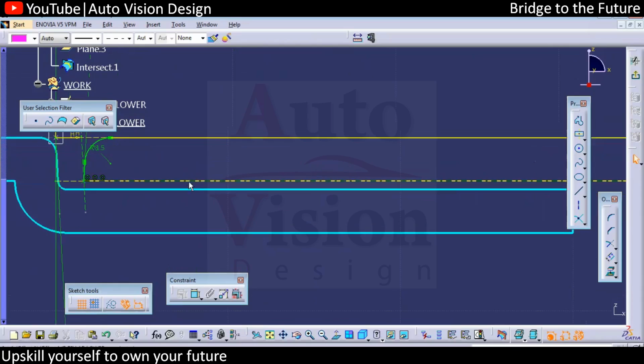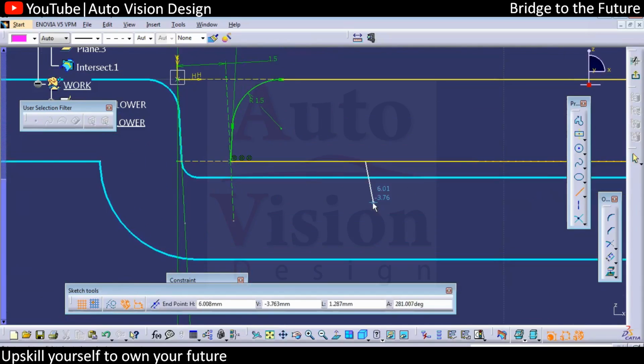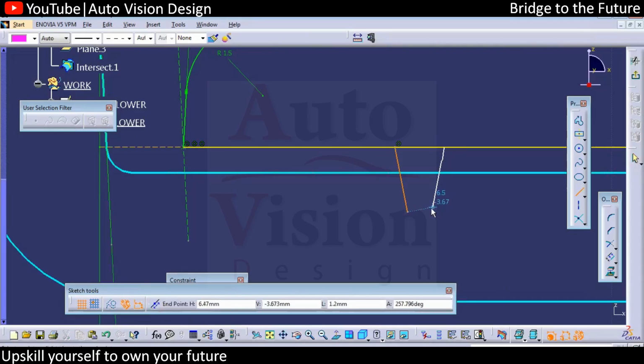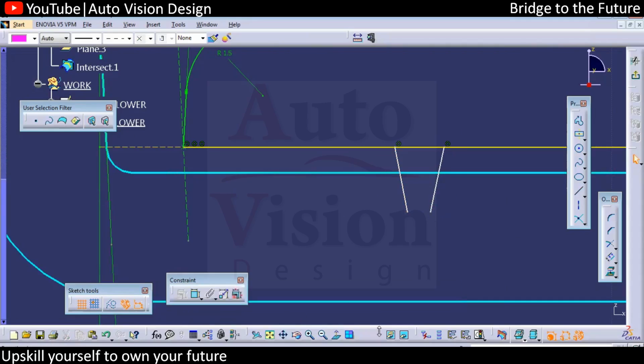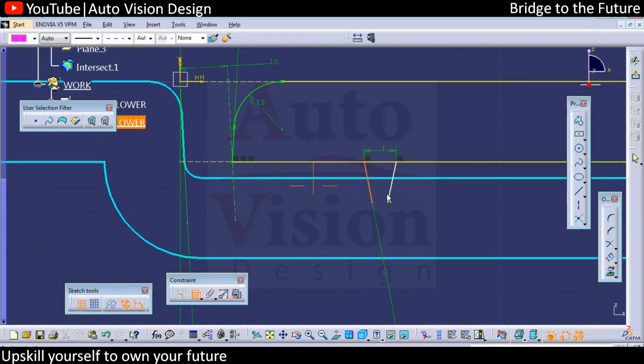Now we will have the touching rib over here, at some distance of equivalent area. So that touching rib we need to add with 0.5. Root thickness we need to maintain as 1. So the distance between these two ribs we're going to create as 1. These two have to be a draft of 0.5 to the tooling line.